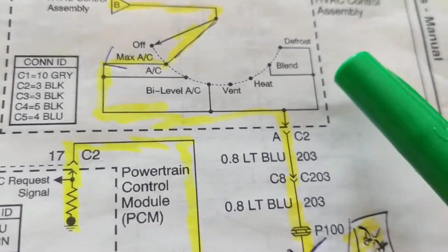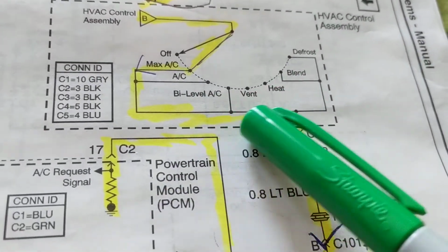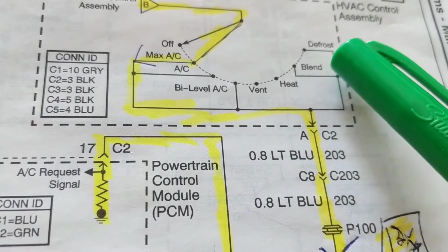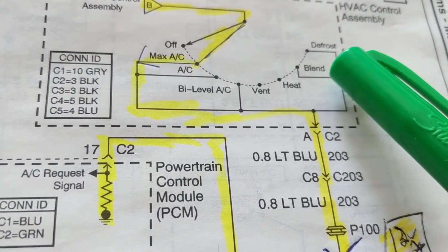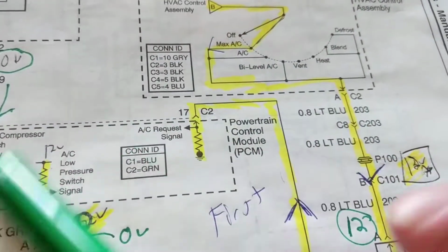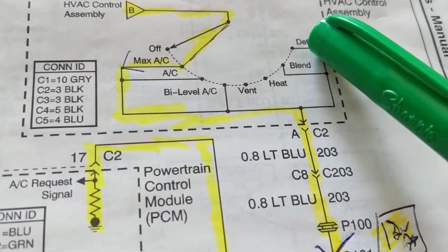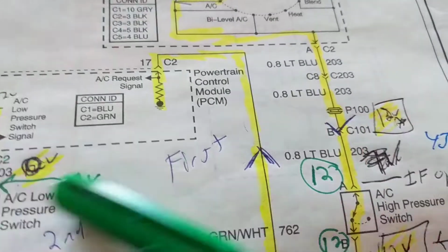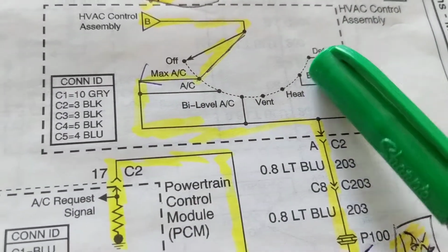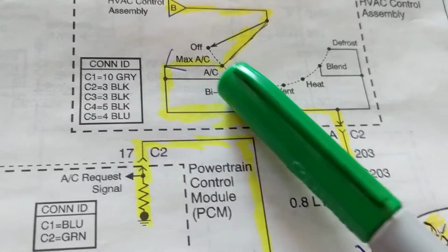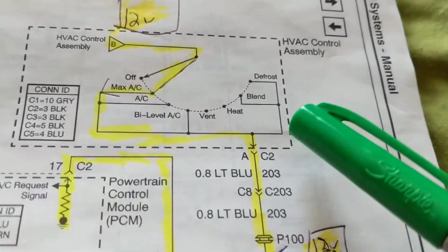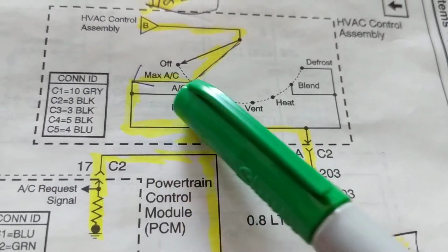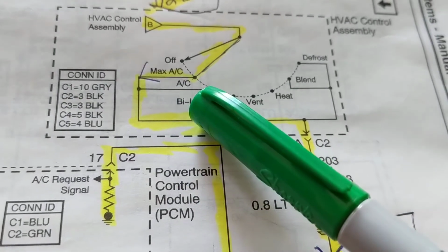Now, other thing is, if I don't get AC, the first thing I do is I'm going to put the switch to defrost. I want to see at least on the front windshield getting cold air. If they're not, that means I pretty much have an AC problem. If I'm getting cold air in the defroster, that means the system is working. However, I'm not getting anything in the other selections. Now, could be a couple of things. Maybe the switch is stuck on defrost and it's not going to the vents to the passenger or the driver.